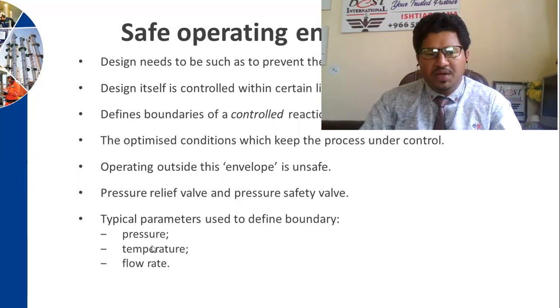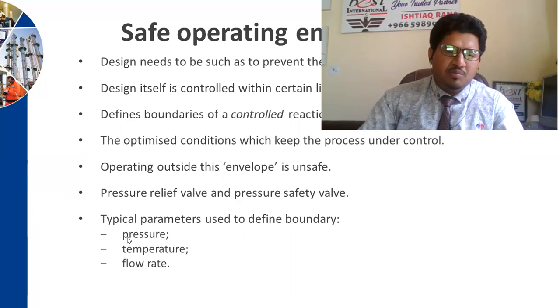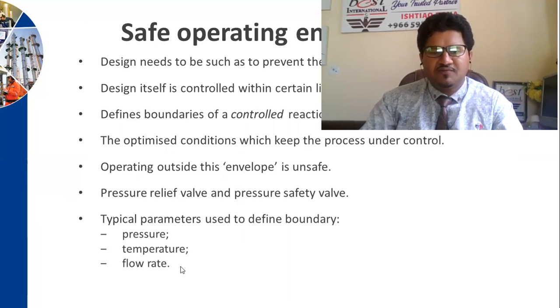Typical parameters could be pressure, temperature, and flow rate. So remember PTF: pressure, temperature, and flow rate. And on the other side, the pressure relief valve, PRV, and the pressure safety valve, PSV. Anytime you are operating outside the envelope, it's unsafe.